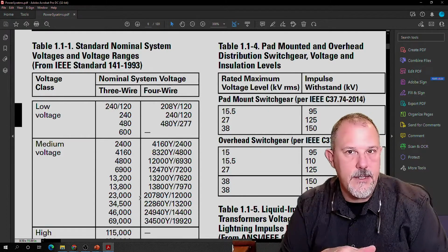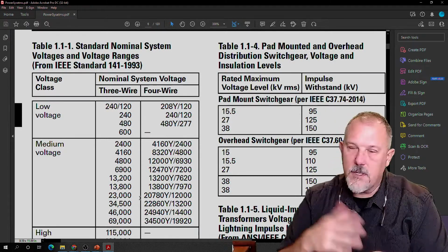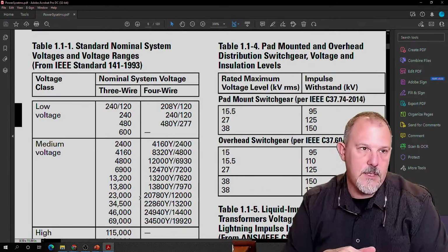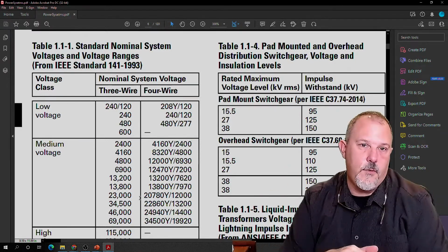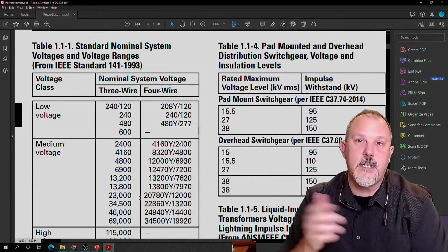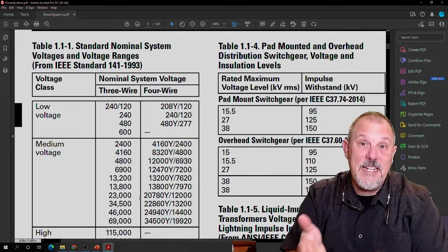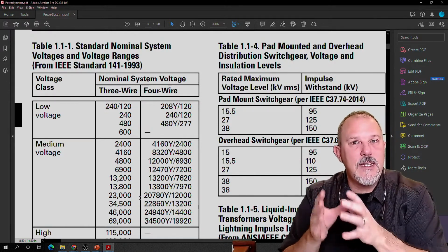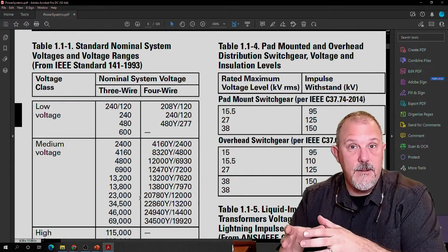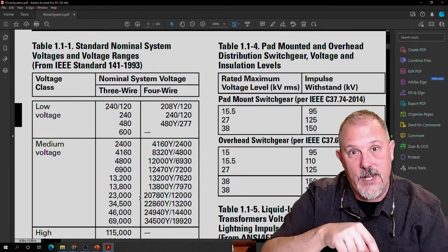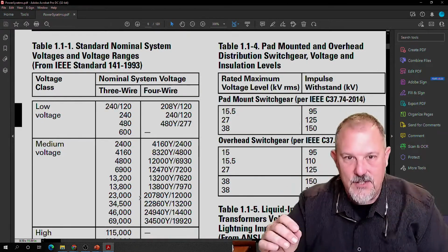You don't see that on other applications like lighting, etc. They'll put, this is 277 volt lighting, or this is 240 volt equipment. Your stove is 240. It's rated 240. It's not rated something different. So although some older equipment are rated 115 volts, typically the only time you get something that's maybe rated 115 or 460, why they rate it that way is there's a motor inside. So the motor is the driving factor.